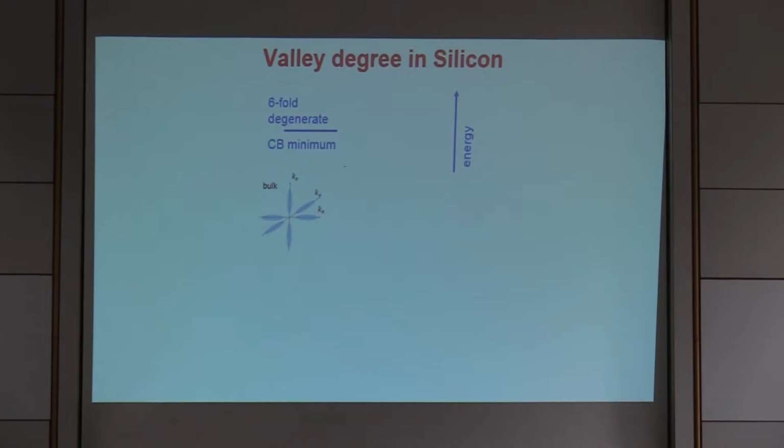So the ground state in bulk silicon is six-fold degenerate. But once we build silicon on top of silicon germanium, we break the planar symmetry due to the strain, and then we separate two-fold and four-fold degeneracy. But the ground state, in this case, is still two-fold degenerate. If you want to lift this degeneracy, you can do it by building a perfect, ideal silicon quantum well.